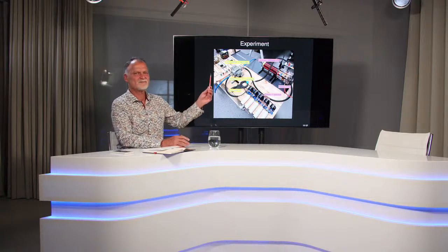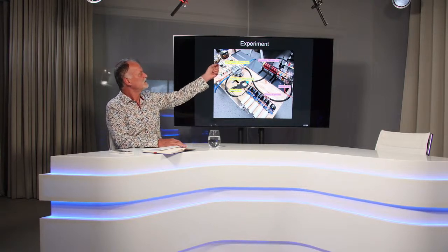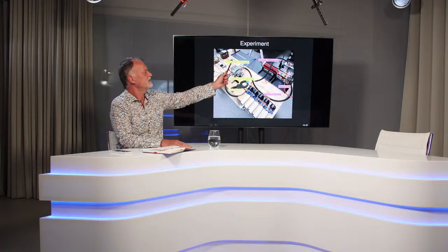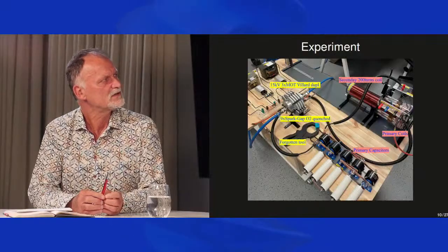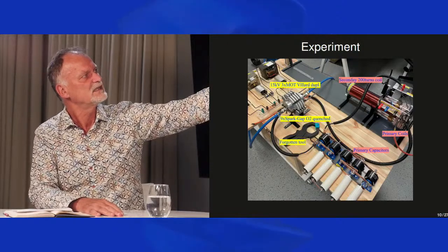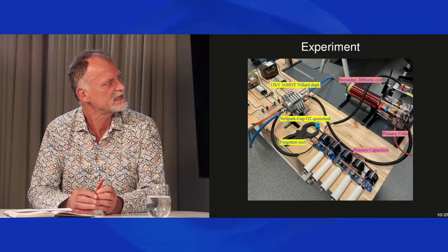So this is a picture of one of our Tesla transformers, version number 16 or so, that we built in our laboratory. Here you see a high voltage transformer, which is made of three microwave oven transformers. Each, I believe, provides up to 15 kilovolts with the Villard doubler. So at the end, we have something like 30 or 40 kilovolts, right?